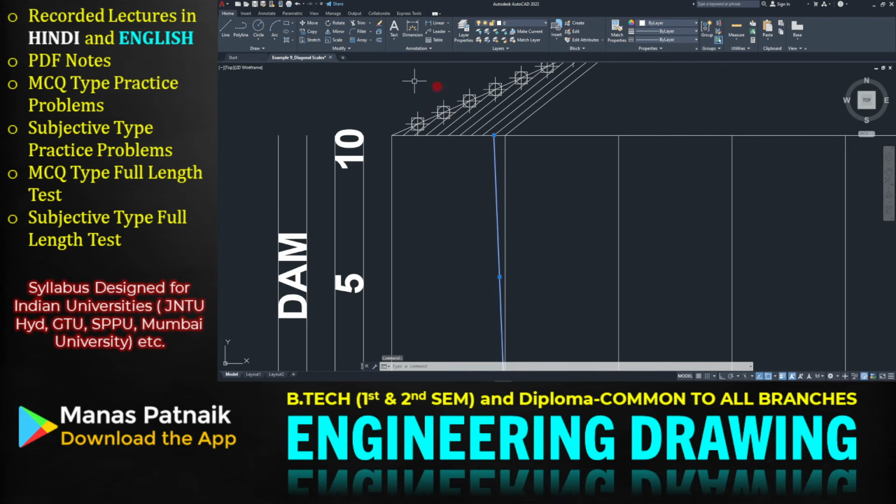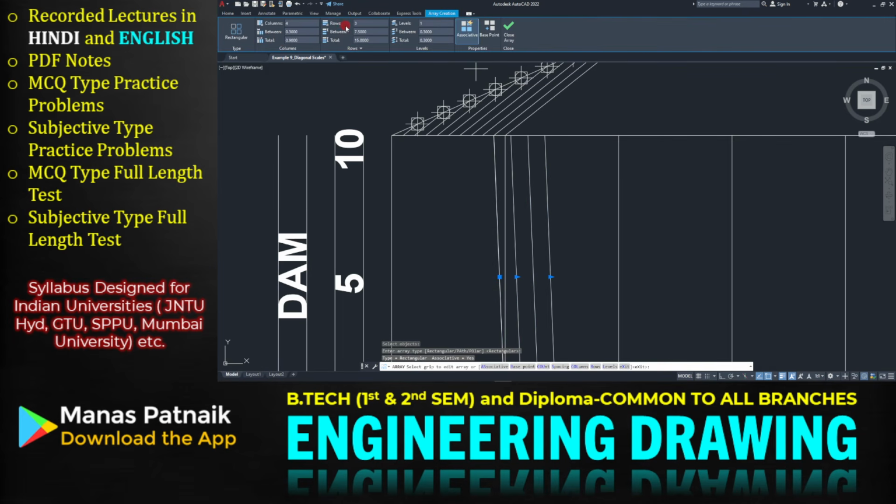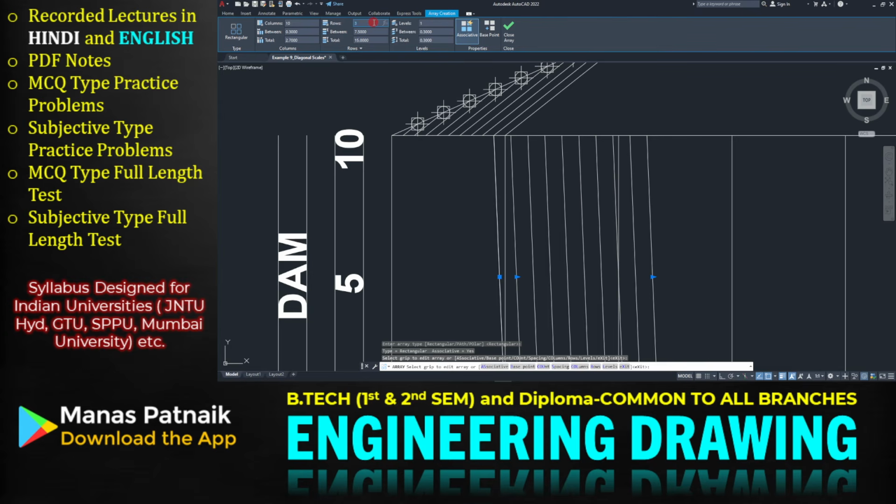Now, you can click on this, go for the copy command. This is the base point. You can make multiple copies. Or you can also go for the array command. Let me demonstrate using array command. ARRAY, enter. Select the object. That is going to be my object. Enter again. Rectangular, yes. And right now, what I need is columns. How many? Sir, I need 10. How many rows? Sir, I need 1.